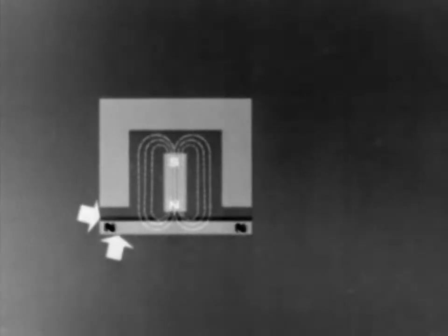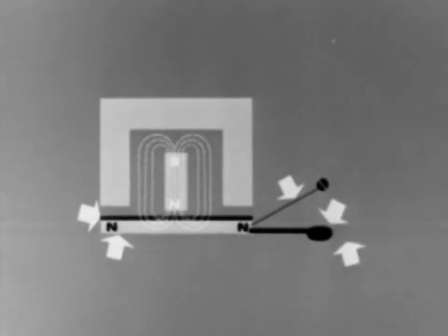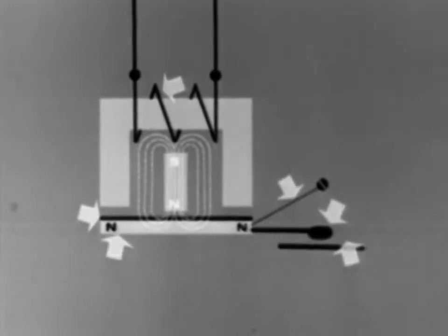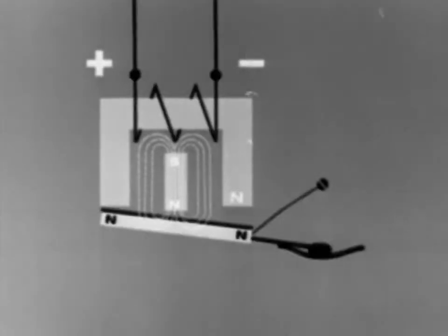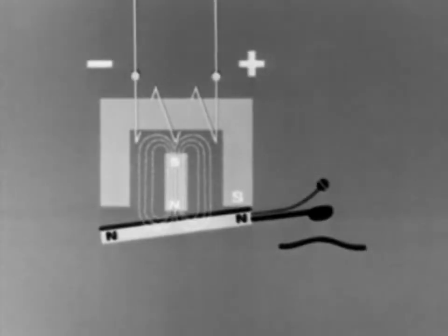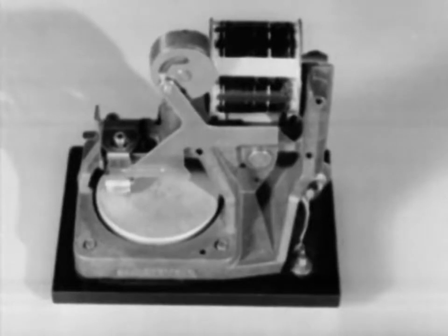Another audible signaling device is the telephone buzzer. This device uses a bar magnet, an electromagnet, an armature, a non-magnetic separator, a stabilizing spring, a clapper rod, a diaphragm, and a single-wire coil. As the current changes in the wire, the polarity of the electromagnet changes. As the polarity of the electromagnet changes, it attracts or repels the armature to the core. Here is an actual telephone buzzer in operation.